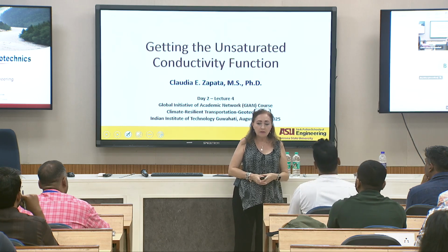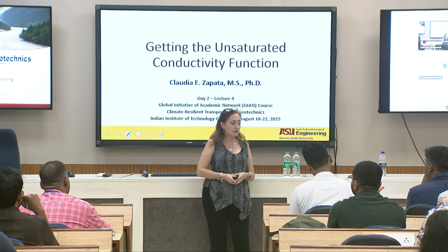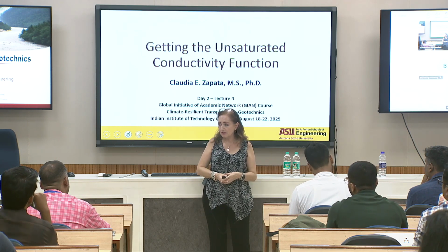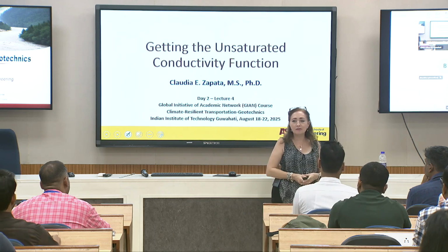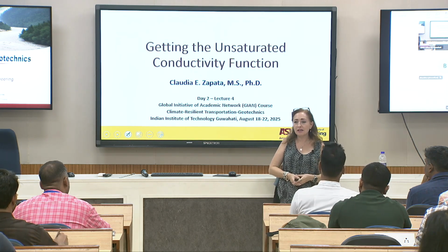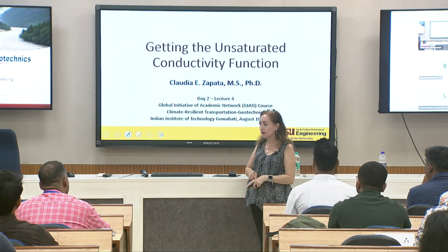Today, and in the first lecture tomorrow, we're going to be talking about seepage analysis and fluid flow, right? And for that, we promised this morning that we were going to get into the unsaturated conductivity function, right? The unsaturated conductivity function.